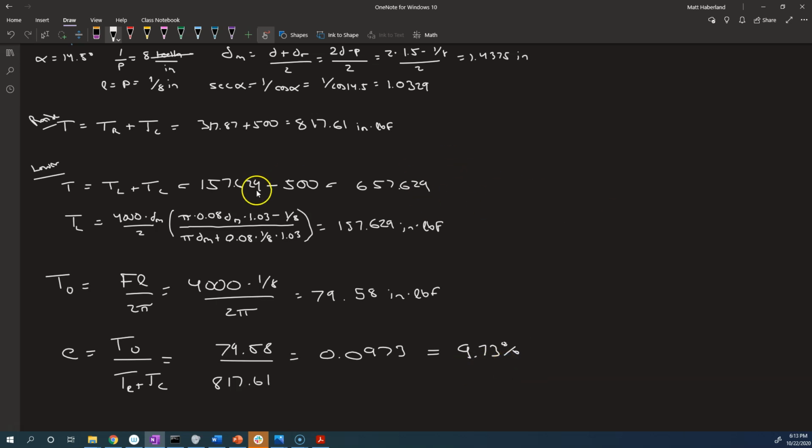Now as you're going through this, be careful. You need to really think about what the full torque required to raise the load is. Notice how I didn't figure out a new letter to use here. I used letter T in both cases for raising and lowering, because the book has already taken up the symbol T subscript R and T subscript L for just the part that's independent of the collar friction. You always need to remember to add that collar friction in there to get the total. So be careful about that when you're solving your problems.